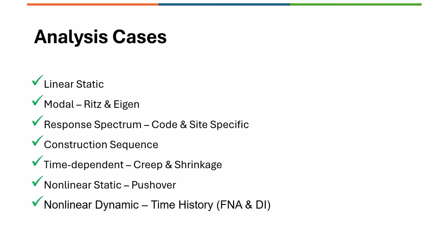So pushover is a lateral sway analysis, which can be used as an alternate to time history analysis, which will be computationally costly. Pushover will help you in resolving that. But I will demonstrate with an example for the pushover. Program is also capable of the time history analysis, dynamic time history analysis, considering the material nonlinearity as well as geometric nonlinearity. So even in time history analysis, it can be based on modal, which is fast nonlinear analysis, or in other words, FNA in short form, or the direct integration step by step. Both are possible.